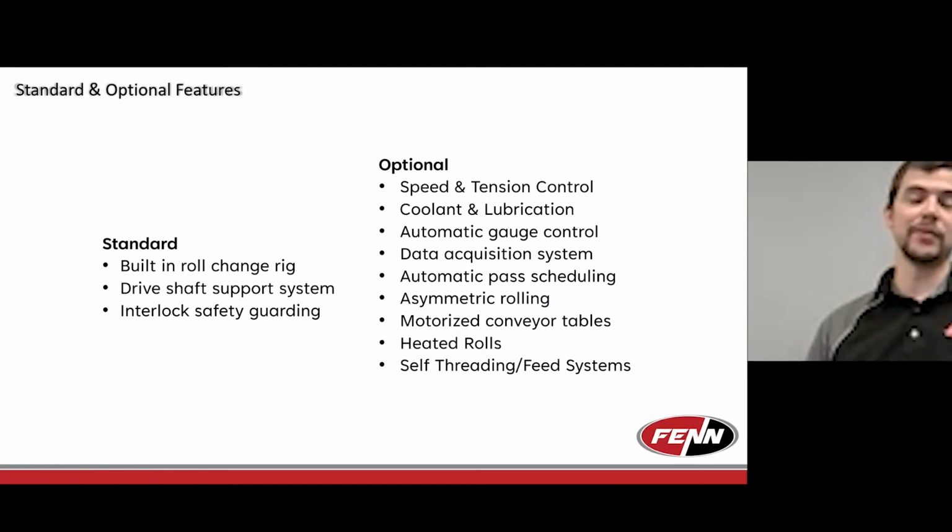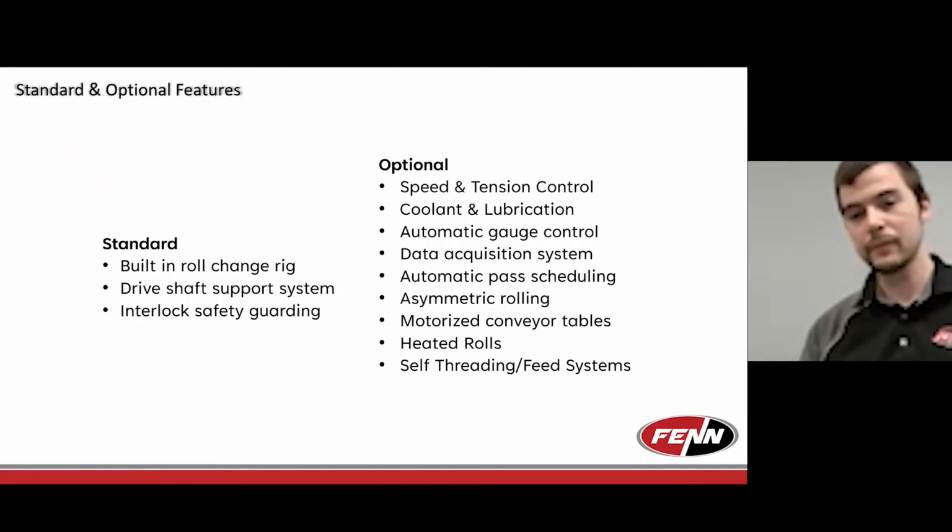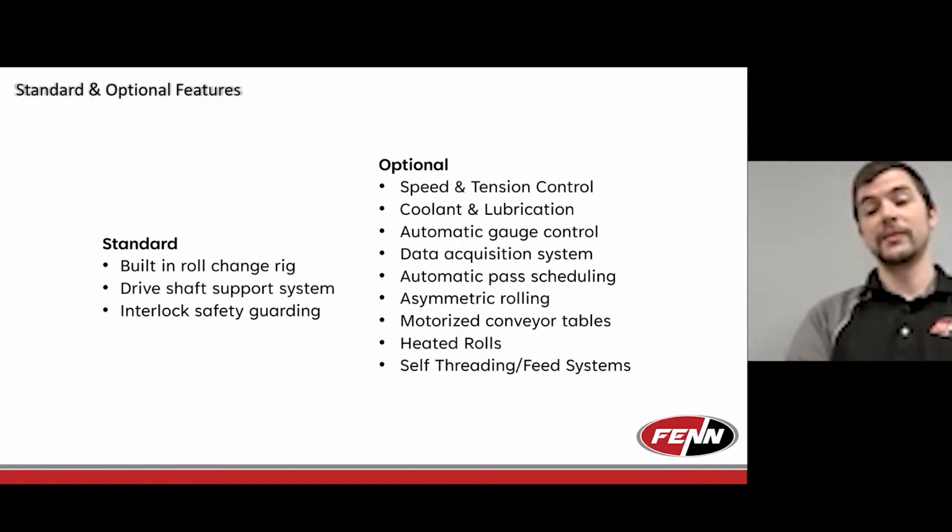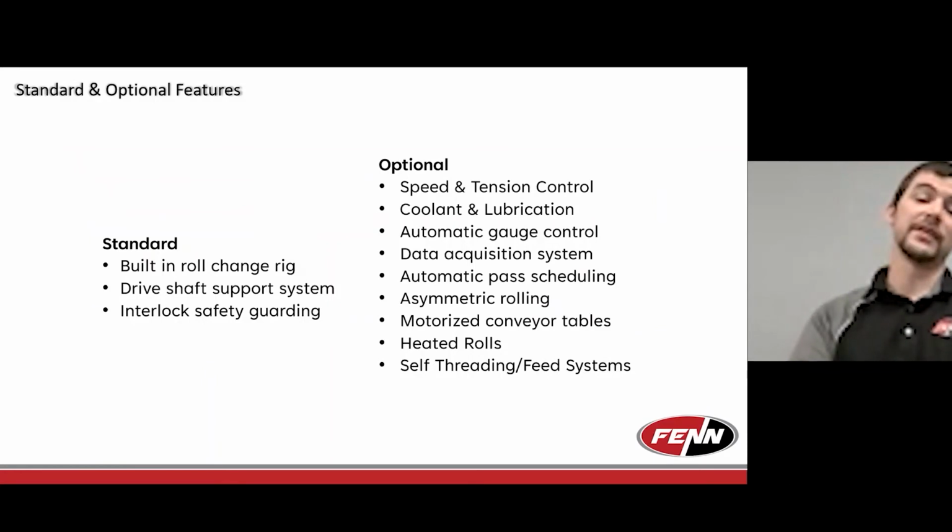And we can provide simple types of manual applicators to complete flow rate nozzles in order to control how much flow and lubricant you're applying as you need, and can even, depending on the type of application, make it fully recirculating.